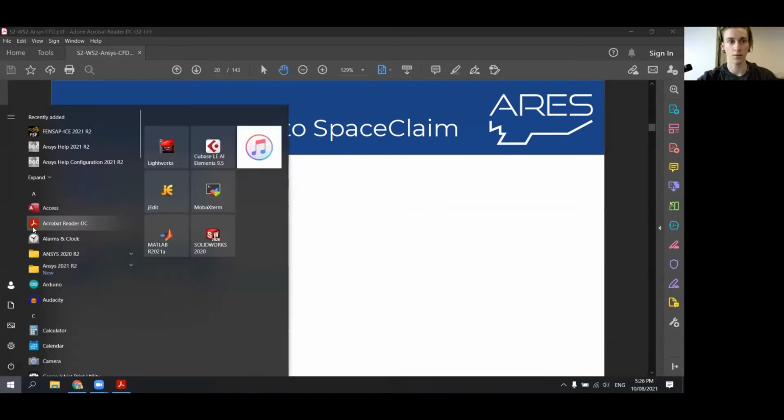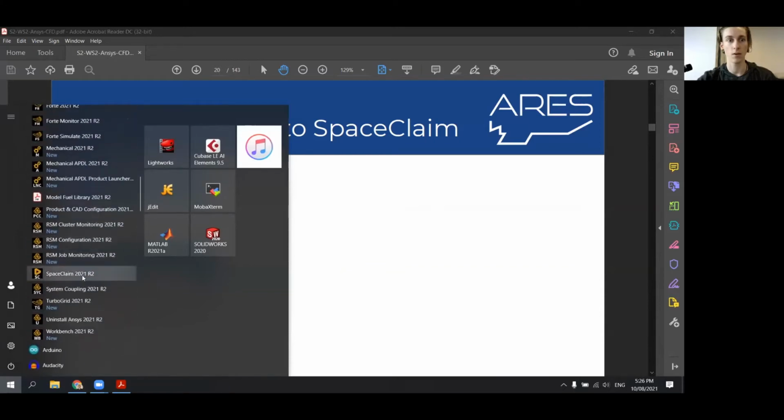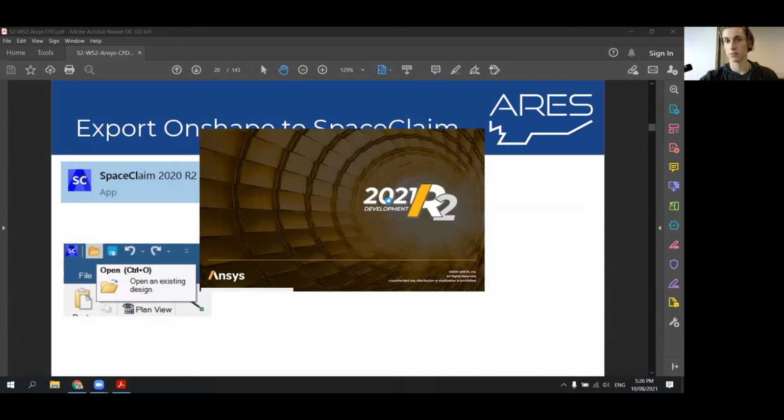So we're going to go to our Ansys software, scroll all the way down to SpaceClaim, which you'll remember is the 3D modeling software in Ansys. And we're going to use SpaceClaim to simplify our 3D model a little bit more, and then we'll put it into Fluent, which is the actual CFD software. So just wait for that to open.